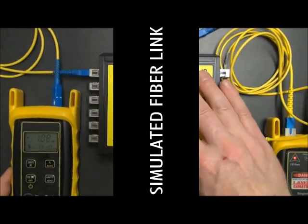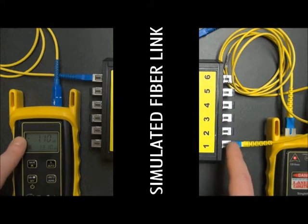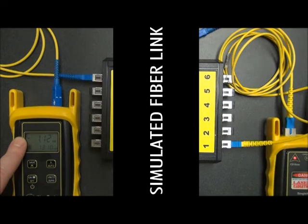Now, as you can see on the power meter, we have a dB reading. It says roughly minus 1.1 dB. Okay, this is how much loss we are reading across this link here. Now, if you look here, there's a negative sign. What this negative sign means is that you are measuring loss of your link. So the light is losing strength as it goes from the light source through to the power meter. Okay, this is what we want to see.